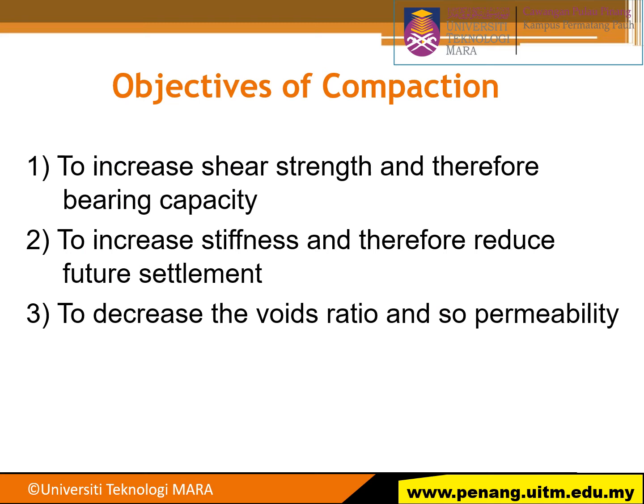Now we go for the objective of compaction. There are three objectives. First is to increase the shear strength and bearing capacity of soil, right? Number two, to increase the stiffness and therefore reduce future settlement. And number three, decrease the void ratio and also reduce the permeability value.